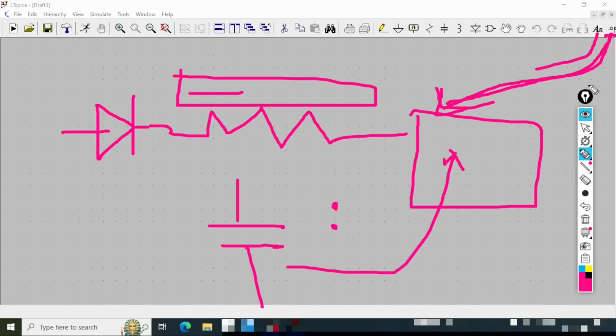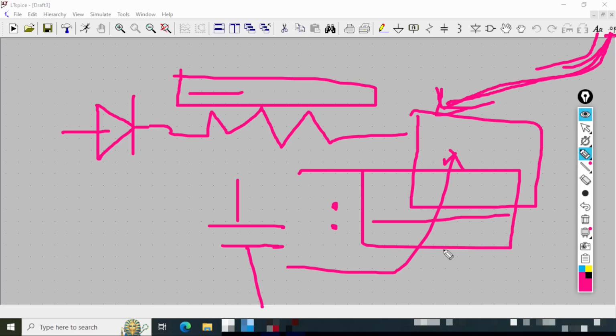So those all commands which are very much native to spice, you can insert them using this particular option and it will open up a text box and then you can write the commands by hand. Obviously, you will have some assistance from the LTSpice window while you are writing. However, the basic thing is you have to learn the spice language. And this is the reason I have covered the spice language at the very beginning and then I am coming to this particular GUI so that your knowledge is complete. And now when we are diving into the schematic design, and then we are plugging in the spice analysis and all the spice commands, you are well ready.